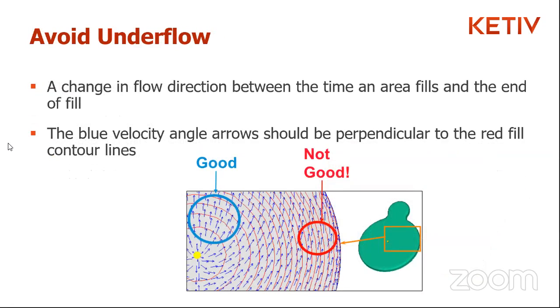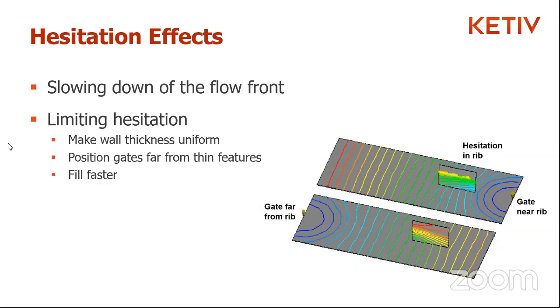Yeah, one of the interesting things about that is the stall drops the melt temperature and creates a higher viscosity. So it's a domino effect. And even today, there's a great chance that someone might choose to put the gate near that hesitation to try to force it in there, but you just aggravate that hesitation, ironically. To your point, Nikhil, where you place that gate and start building that mold is a built-in iteration in order to compensate. Yeah, absolutely.